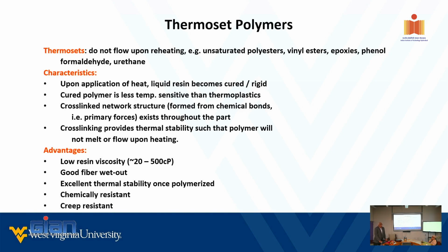Okay. We did not find a major difference in durability between epoxy and vinyl ester. When I say durability, I'm particularly talking about the exposure to pH values. You know what a pH is, ranging from 1 to 14, whereas typically we try not to get the glass exposed to high pH like 12 or 13 because you are getting into the ASR, alkali silica reaction, problem.